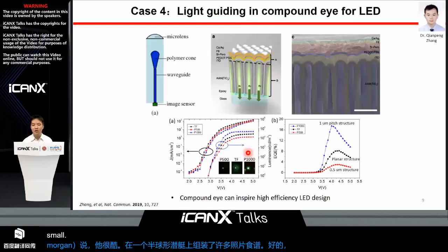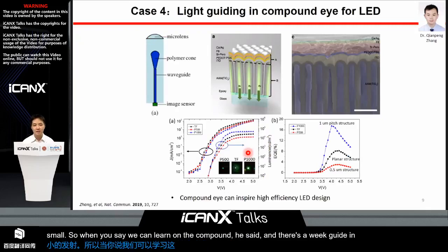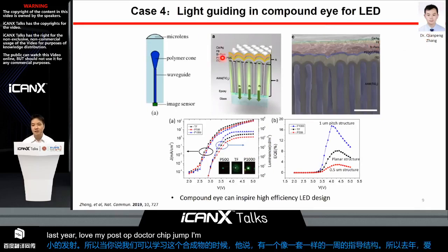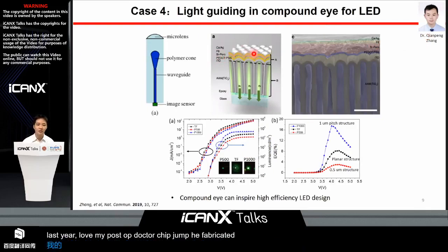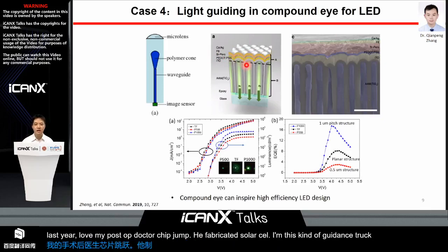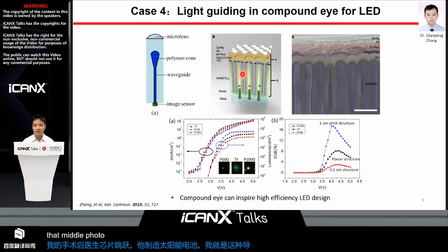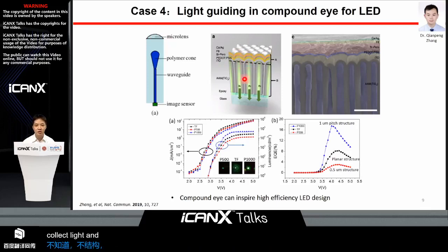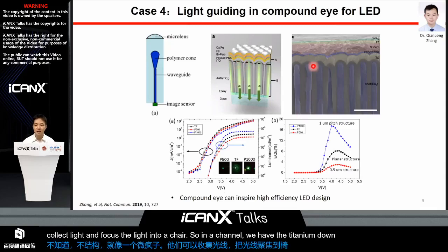So one more thing we can learn from the compound eye is the waveguiding structure, like I said. Last year, one of my postdocs, Dr. Qianpeng Jiang, fabricated a perovskite LED on this kind of waveguiding structure. So we call that a nanophotonic LED device. On the top, there's a nano dome structure, just like a microlens, that can collect the light and focus the light into the channel. In the channel, we have the titanium dioxide waveguiding material.